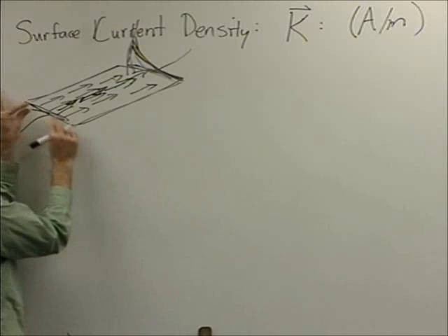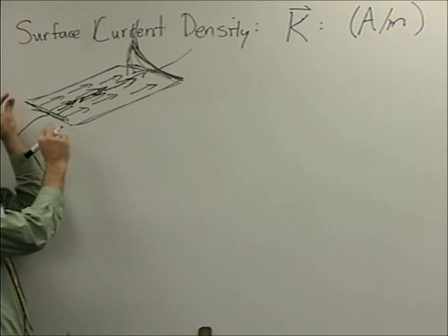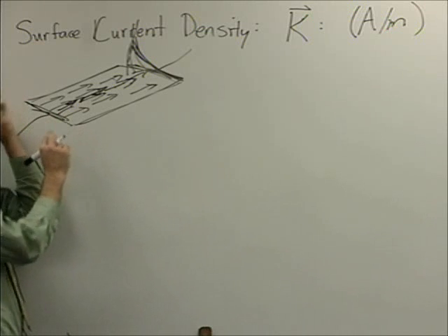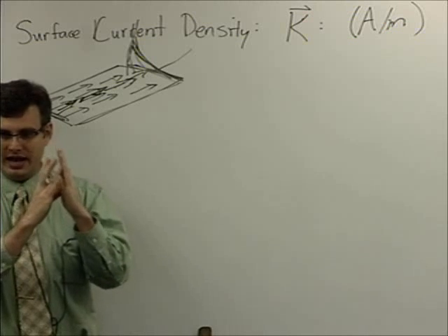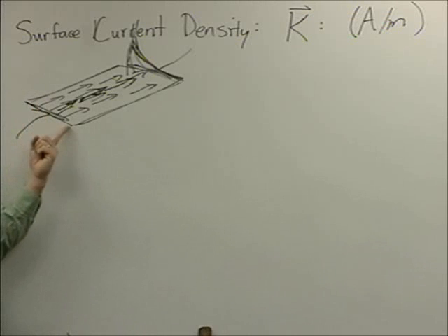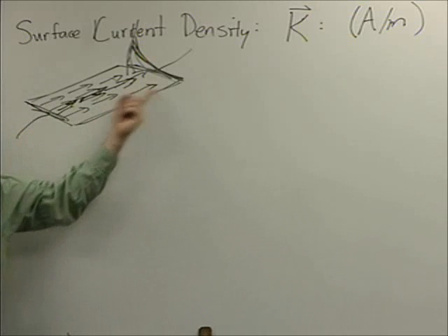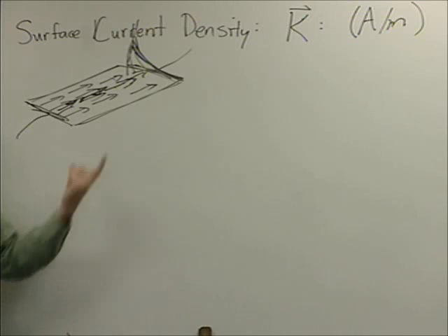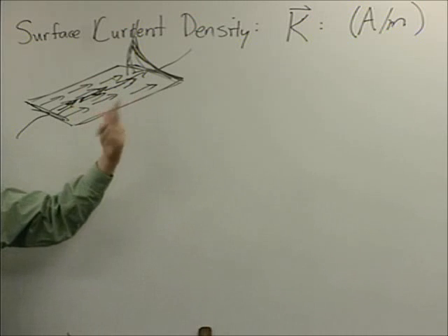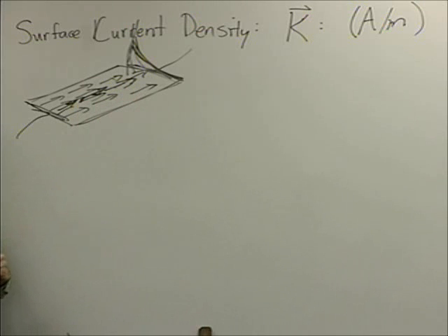And if this is a very thin piece of metal with a known conductivity, then what that means is you're actually constricting the path of that current. And so by measuring the resistance of the ends of these 2 points, you are equivalently measuring the magnetic field. It's an inferred magnetic field measurement. So you just put this up to some ohm meter circuitry and make that measurement that way.